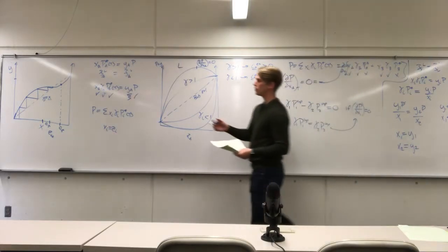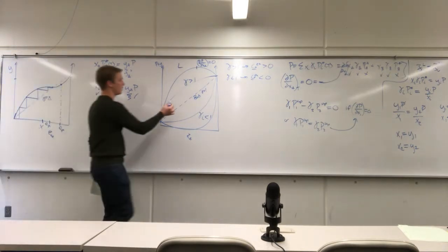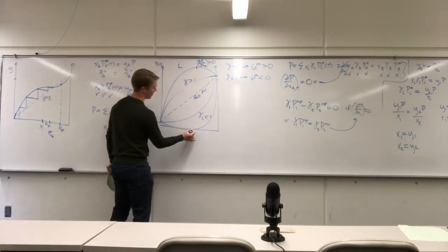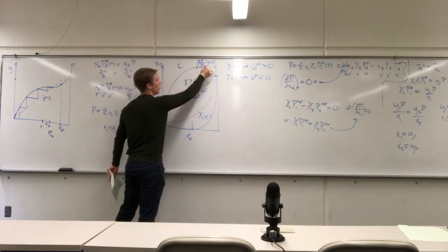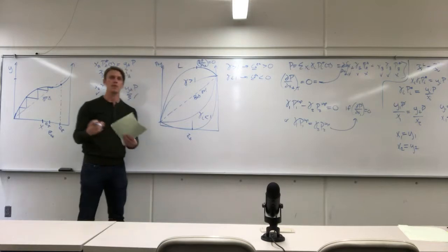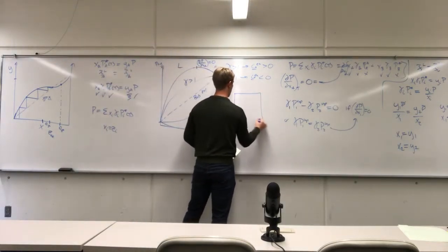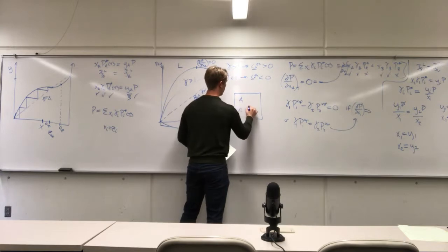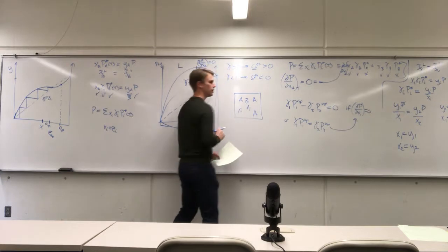Because when you have, for example, an azeotrope and lots of non-ideality, right? So same example here on the PXY diagram, if I go up here, you can see that as I add more of the volatile species, it wants to boil less. Now, typically how that's going to happen is when you have a mixture of A and B. So in this case here, I have a lot of A and a little bit of B.